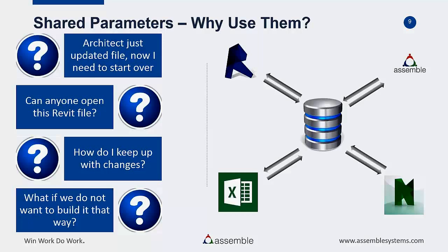If you don't have access to open Revit and you want to make changes to some of the properties of an element, so you can either sort it or communicate back to the person who's actually using Revit to model the building, you can use a shared parameter.